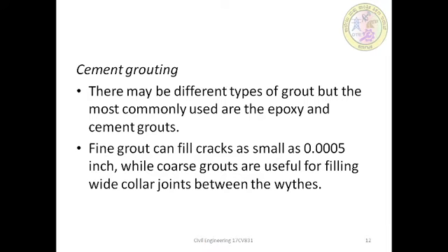The cement grout consists of one part of Portland cement and half a part of type S hydrated lime or half part of fly ash, which may be used for repairing earthquake damage in unreinforced masonry.